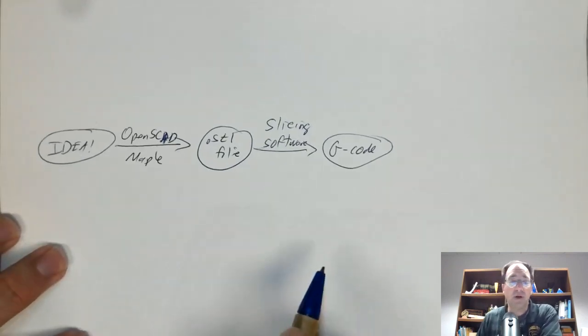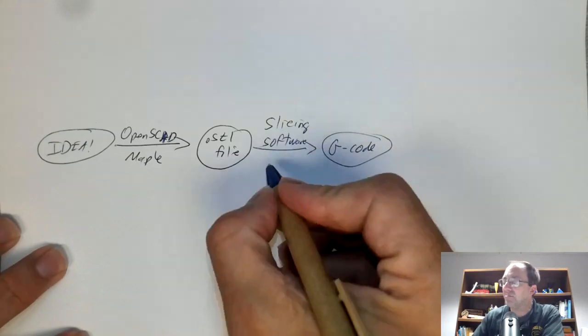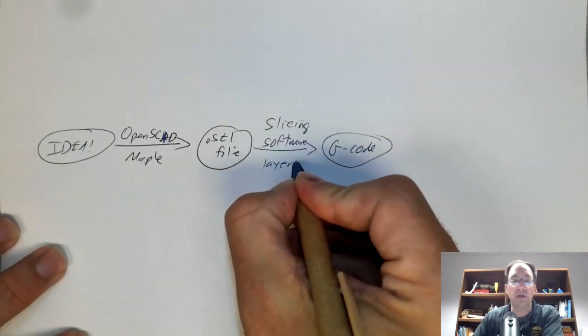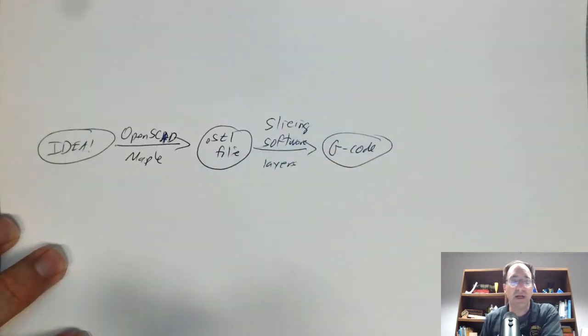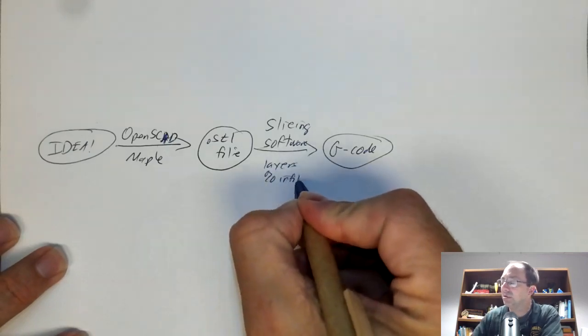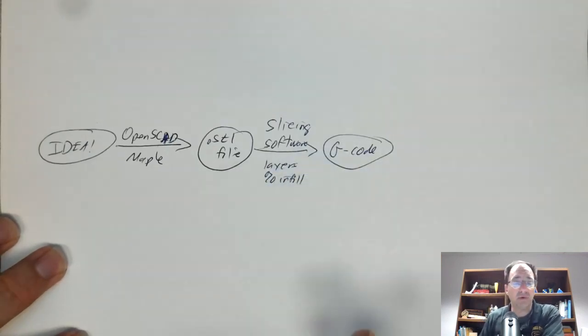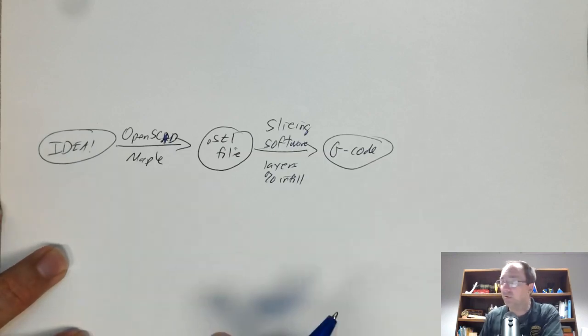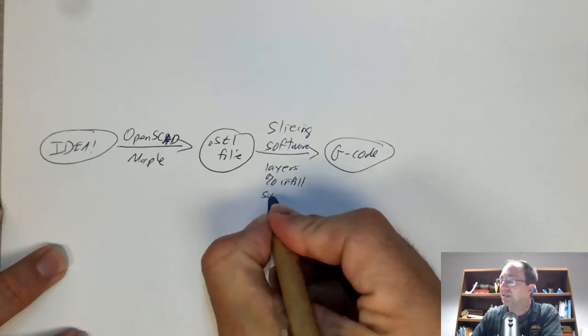But one of the things to be aware of is even now you're going to have to think about how many layers am I going to need for like the top or bottom of my objects. What sort of infill will I want? Generally, 3D printed objects aren't 100% solid, so you're going to have to decide for some number less than that. If you went 0%, that would mean it was hollow, basically, which is sometimes what you want. There's even things like supports.